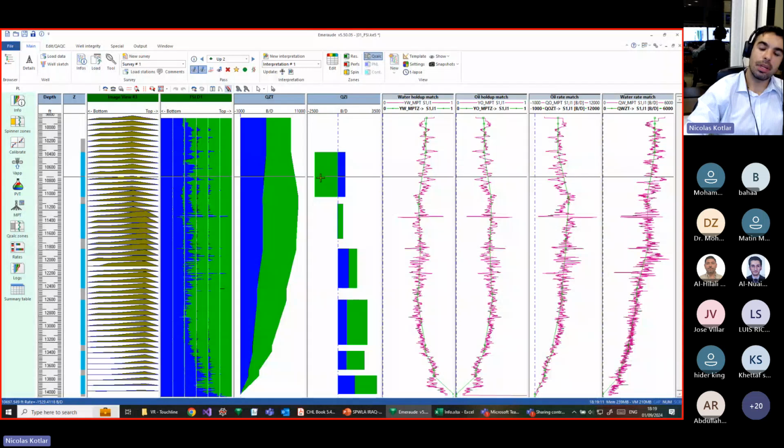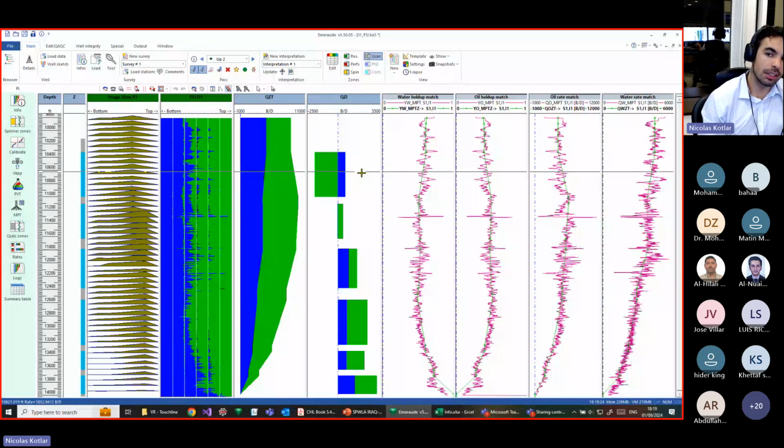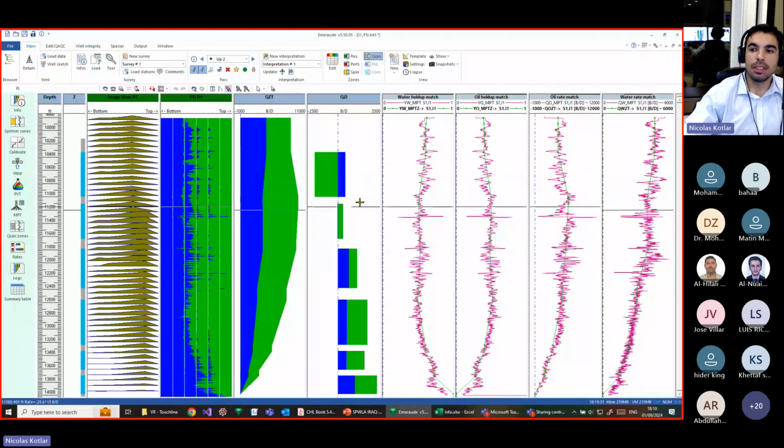That is, this upper inflow zone produces water and injects oil, right? This is a downhole separator, right? A layer cannot produce one phase and inject another phase at the same time, right? It's either positive drawdown or negative drawdown, right? So this is a consequence of the calculation method that we use.